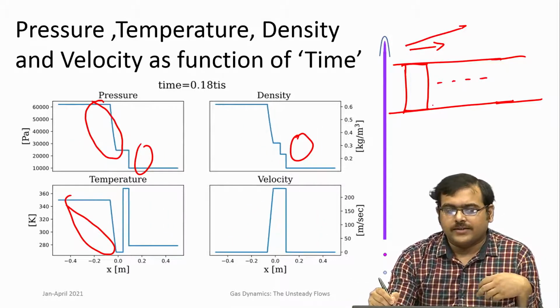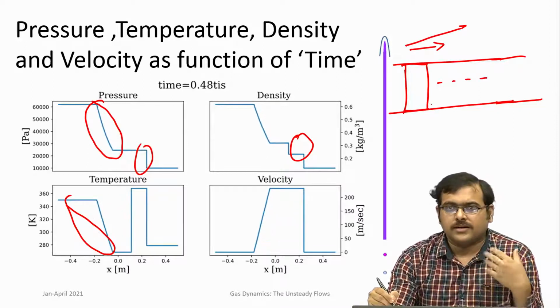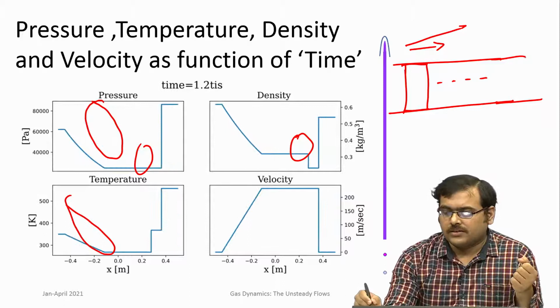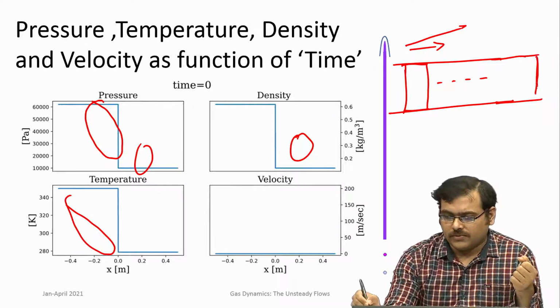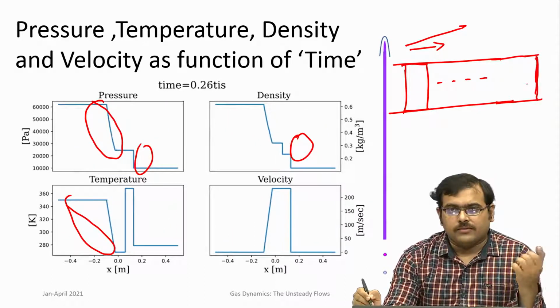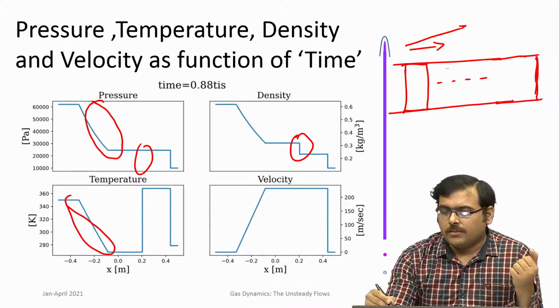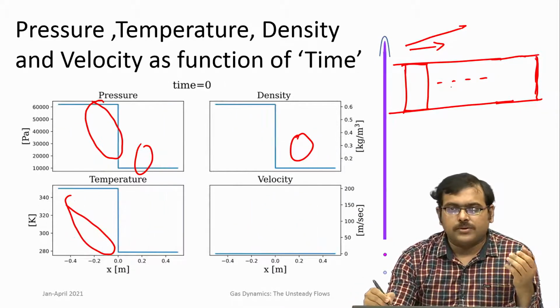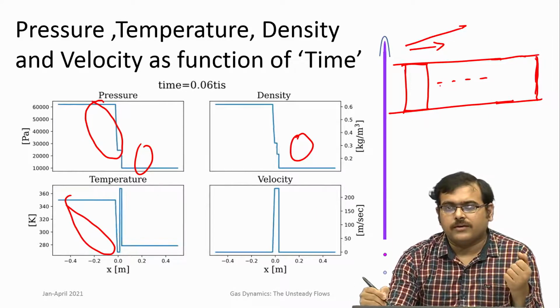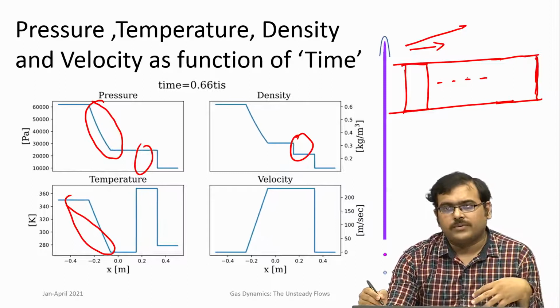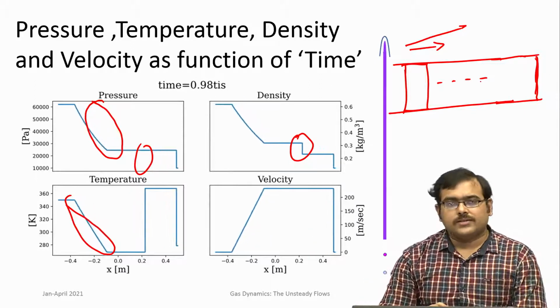Later if this is accelerated to higher and higher speeds, then these compression waves catch up and later on form a shock, which was the piston analogy that we discussed during the formation of shock waves. But in the initial time, how the compression waves move can be solved using the finite waves that we have discussed just now.